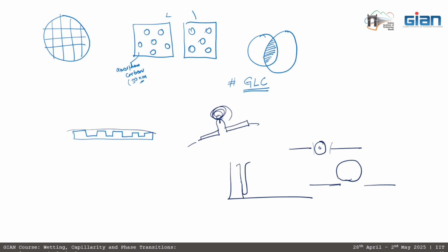They used to do milling, the gallium ion milling. Using SEM they did the milling, and in this milling we have a sequence of gallium ions that bombard the silicon nitride membrane, and they strike out atom by atom, and then we have this pore. Although we see it as a straight line, very thin, this membrane also has a thickness of around 19 nanometers. So it's kind of a channel in one aspect.